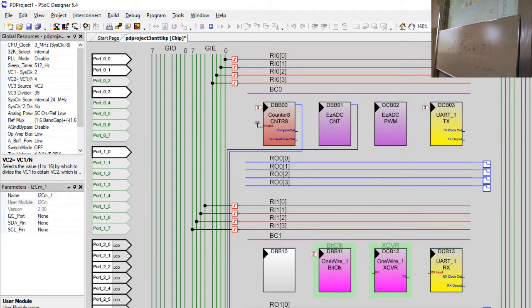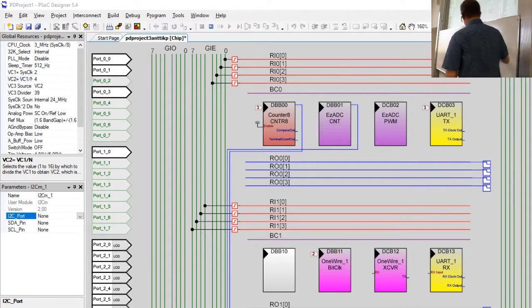But actually this I2C master is software only. It does not take any digital resources, because the timing is quite simple to arrange, fast or slow enough. You just need to fix the port and pins. There's plenty of flexibility where to put the I2C. But you don't have any flexibility since it's actually fixed on the exercise. But anyways, I2C and then SPI.